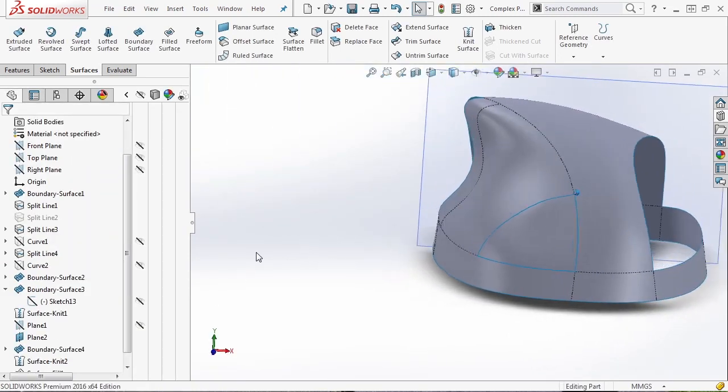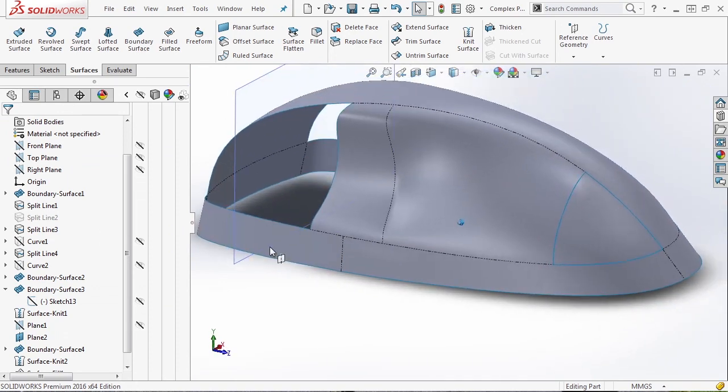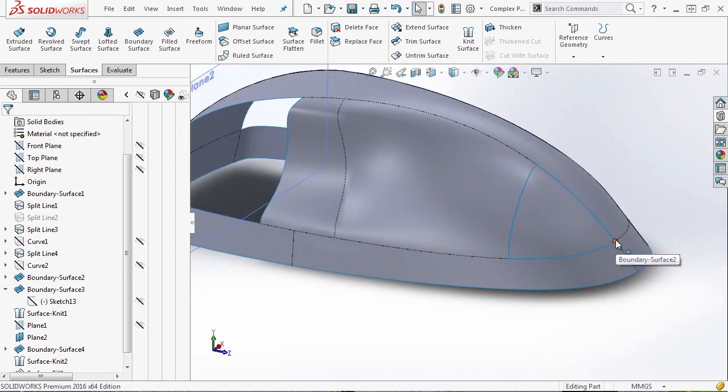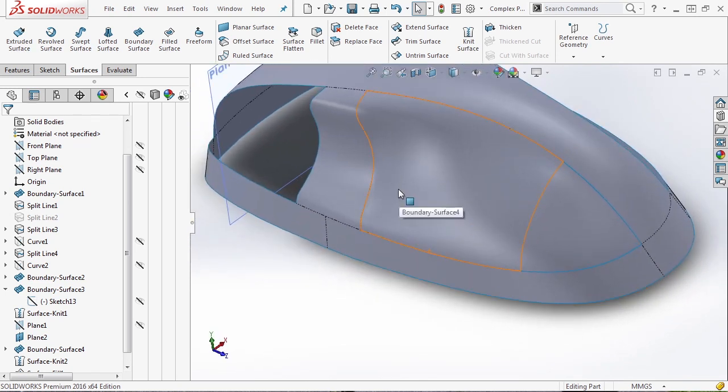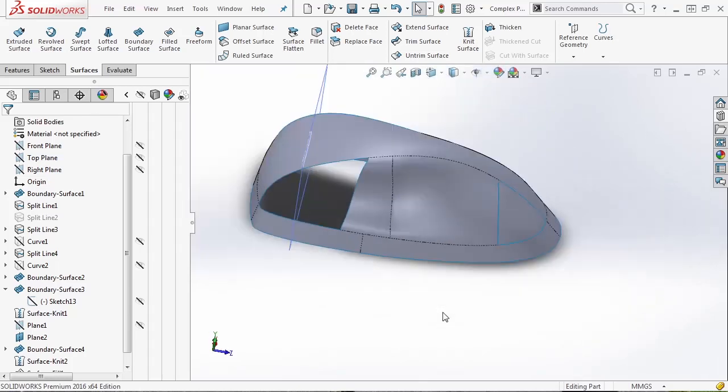So notice that this one patches just fine, whereas the original loft that we tried failed. And oftentimes that does happen when you have a triangular patch. It's not a really good option. So when you fall in that line, try the loft first, but ultimately fall back into the filled surface, but make sure that the final result looks okay.